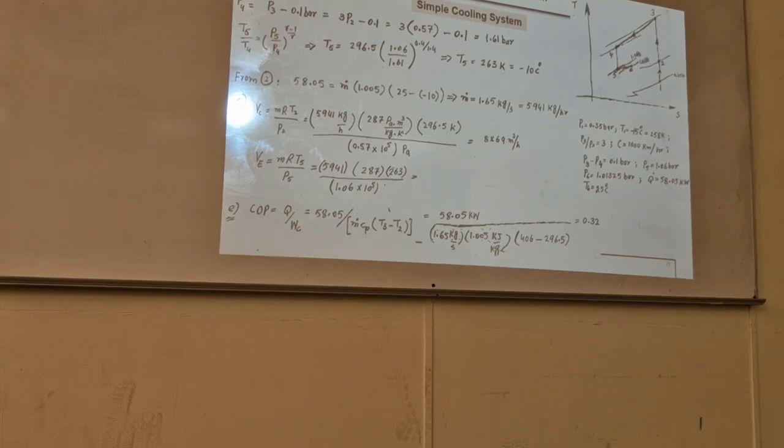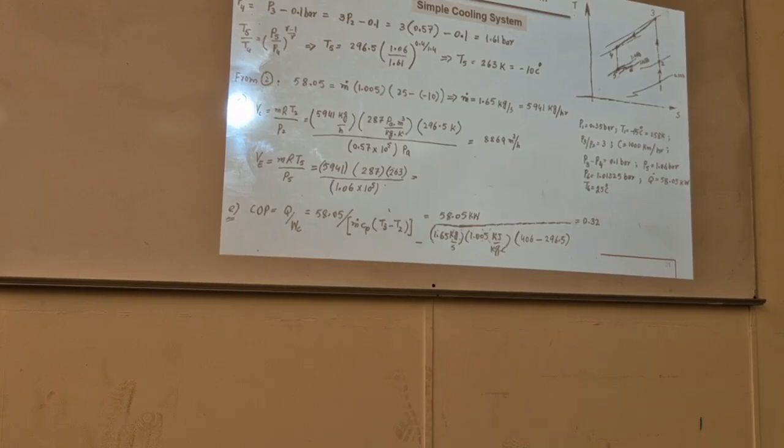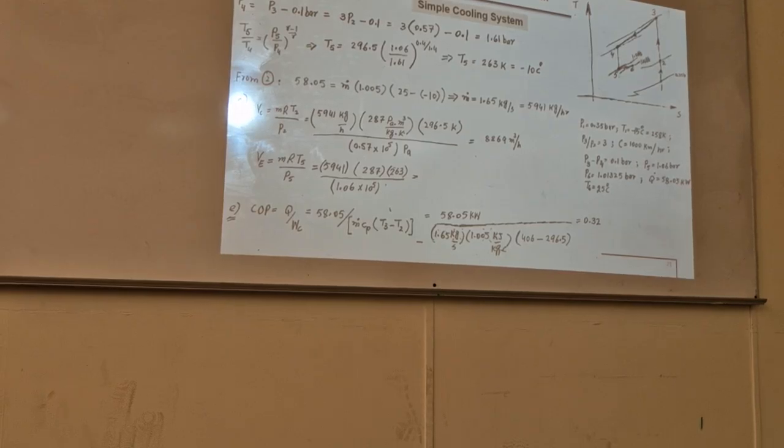Whenever you see a turbine in reality, at the start the blade height is lower. As you move in this direction, blade height is increasing, if you see multi-stage turbines. Similarly in a compressor, if it's a centrifugal compressor, volume drops from inlet to outlet, but the highest one is here. Maximum volume handled by a compressor is at the inlet. It's a design requirement.